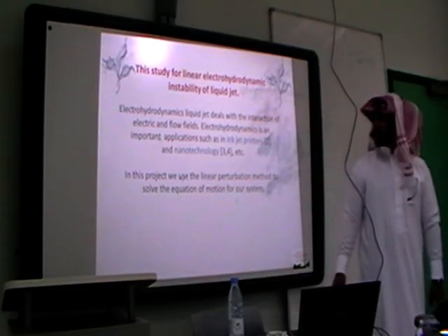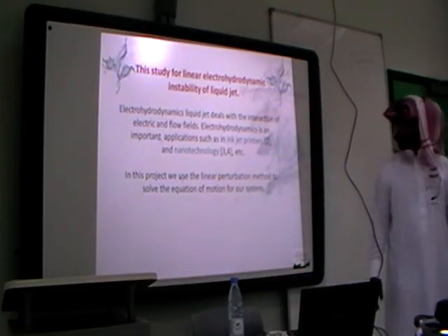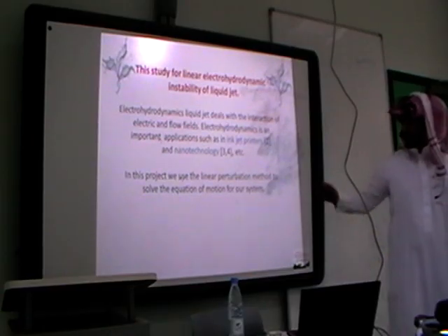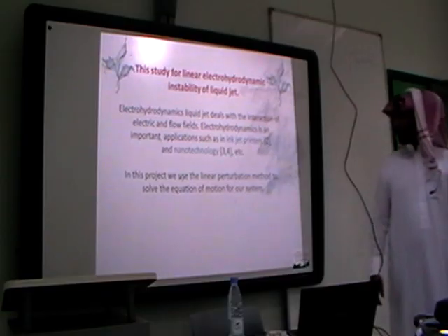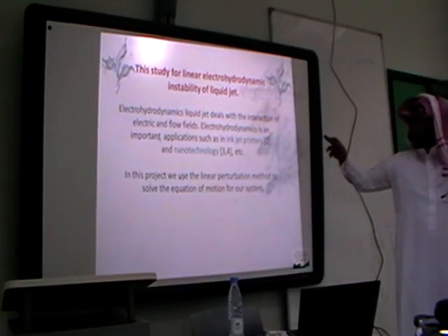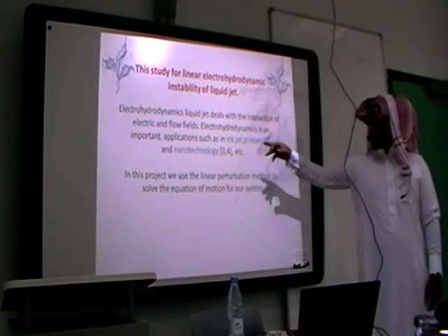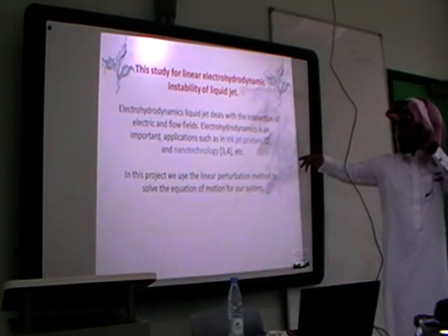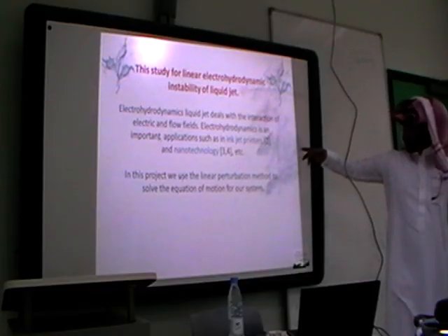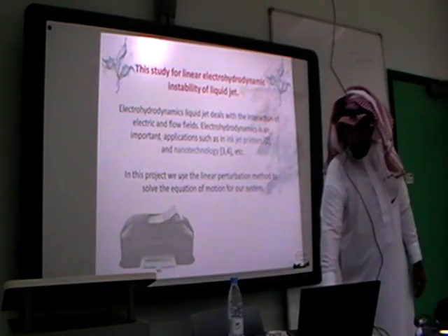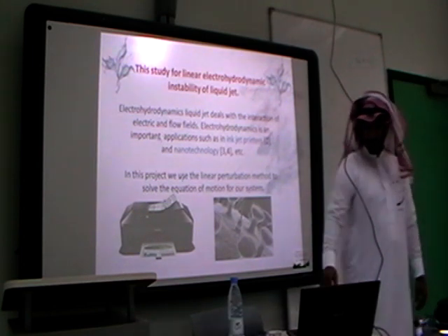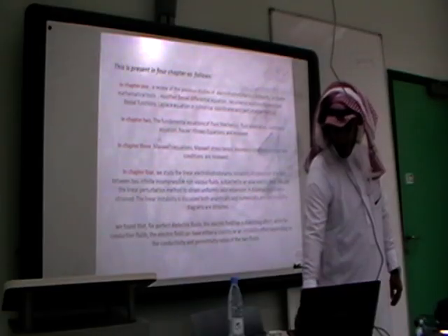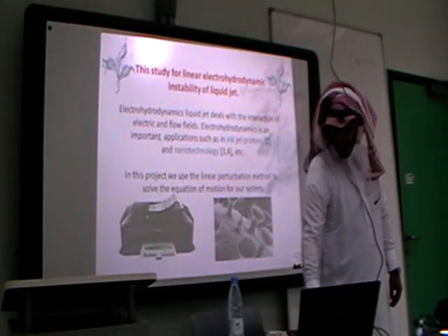This study is about linear electrohydrodynamic and stability of a liquid jet. Electrohydrodynamics of a liquid jet deals with the interaction of the electric field and the fluid. Electrohydrodynamics is important in applications such as inkjet and nanotechnology. In this project, we use the linear perturbation method to solve the equations of motion for our system.